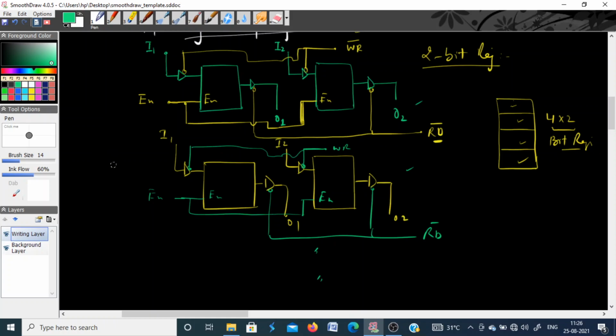So if you have 4 memory locations, you can use a 2:4 decoder, which will have 2 address lines, A0, A1, and of course it has 4 outputs. Okay, and each output of this decoder is connected to one of the enable pins of these registers. So it may be connected to this, may be connected to this, and similarly the rest of the 2 outputs are connected to the rest of the 2 registers that I have not drawn. Okay,